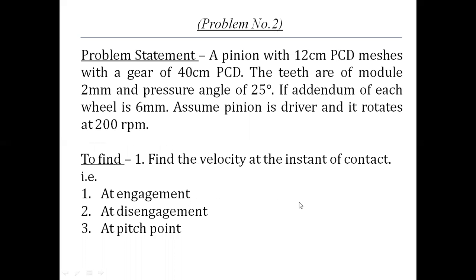The problem statement is that a pinion with 12 centimeter pitch circle diameter meshes with a gear of 40 centimeter pitch circle diameter. The teeth are of module 2 mm and pressure angle of 25 degrees. The addendum of each wheel is 6 mm. Assume the pinion is the driver and it rotates at 200 revolutions per minute.